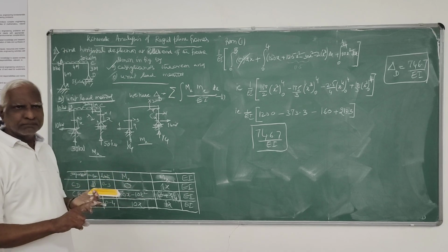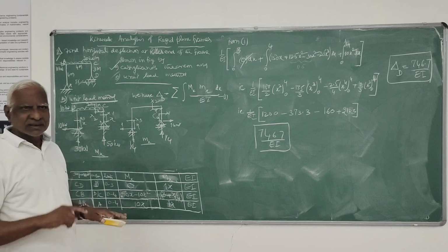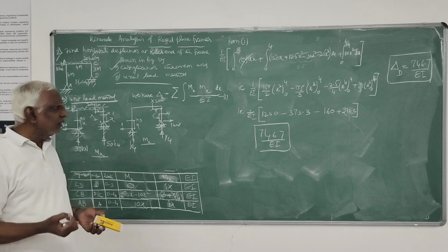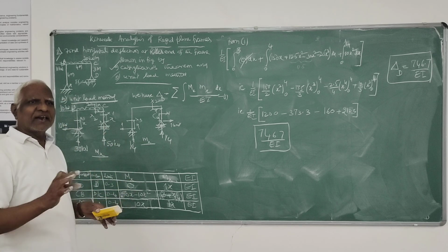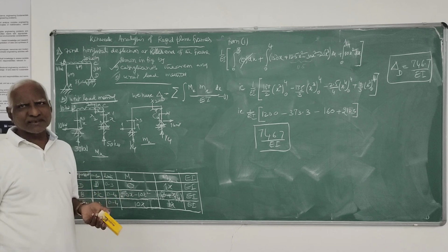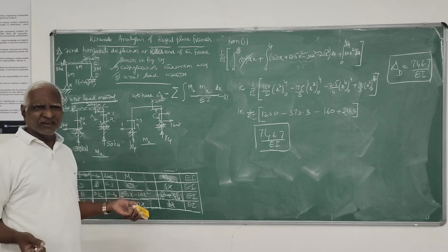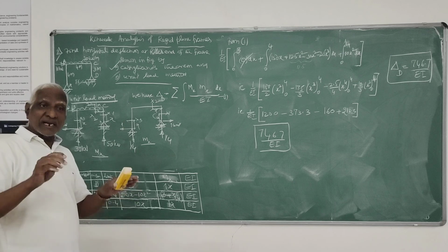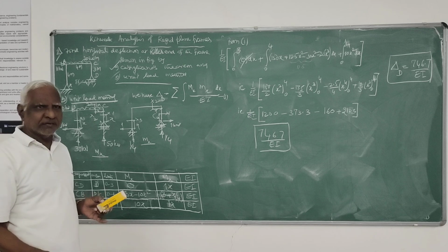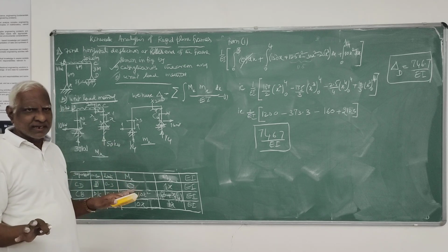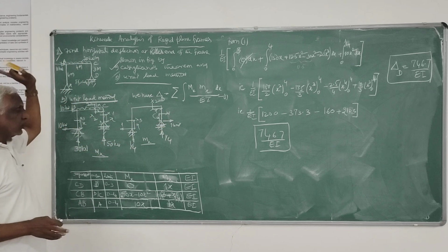We have completed beams and trusses, rigid plane frames. So with this the strain energy method is over. One simple example, just how to find total strain energy stored and how to equate the total strain energy to external work done, and from that how to find delta. If they ask only by strain energy, the limitation is that only one load should be there. One load, one deflection, no other load. We cannot have multiple loads and all those things. It is only one load.